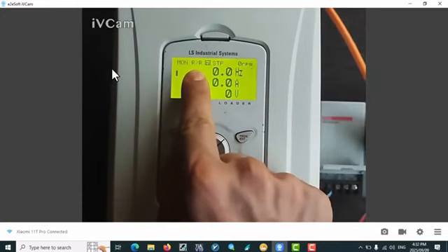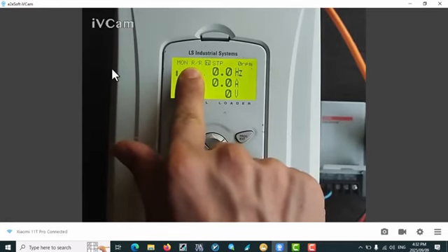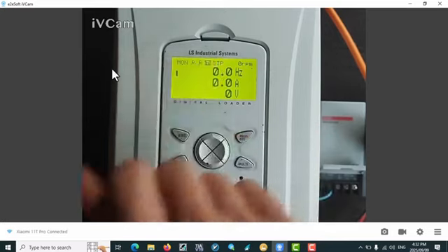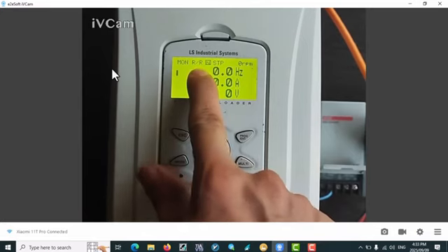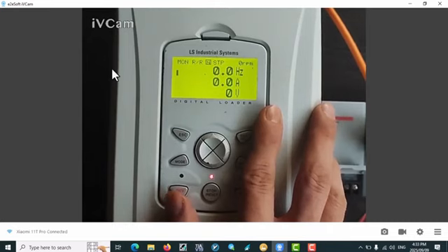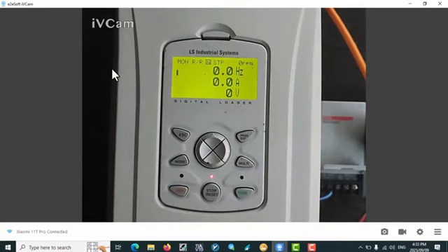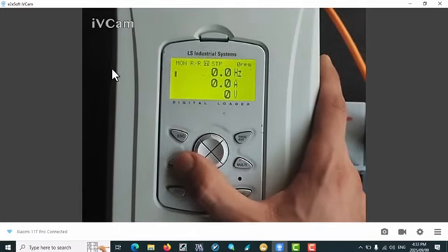If we go back, you'll see that our frequency setting is now coming from RS485, it shows the letter R, and our start/stop is also controlled via the network. So both our frequency reference and our start/stop reference are coming from the network. So using parameters DRVSF6 and DRVSF7, we were able to configure this for the inverter. That means we have to send the frequency value to the inverter via the network, and the start/stop command also comes from the network. But where are the network-related settings configured?